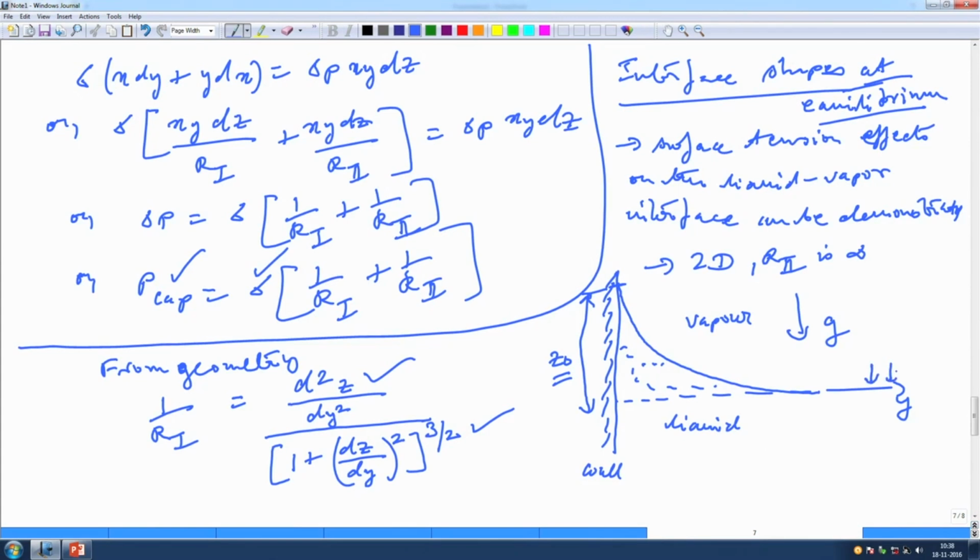Here the interface is basically flat. So, the two pressures of the liquid and the vapor phase must be the same, there is no interfacial curvature. Even if you apply the Young-Laplace equation there, the radius of curvature R1 is infinite, therefore the capillary pressure is 0. That implies that the pressures in the liquid phase and the vapor phase are the same.